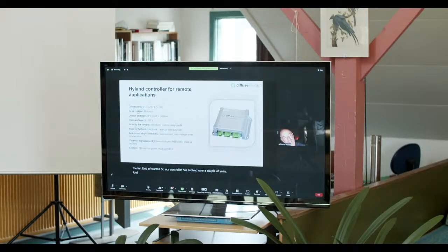And I guess the biggest challenge for us is twofold. One, normally it's assumed that a micro wind turbine is going to have a person around in a storm. Our turbines are mounted out in the middle of nowhere. And so if it does blow 150 kilometers an hour, there's no one there to tether the turbine or shut it down. So we needed to be able to stop the turbine in those situations. So we actually short the windings on the generator, and that stops the turbine in much less than a second.